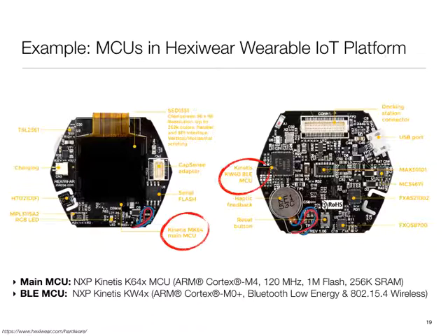It took the motion sensor data and continuously computed what you were doing, like how many steps, are you sitting, walking, stuff like that. But it was nothing other than a Cortex-M processor running specialized software. It was not visible to you as a programmer, but it still existed. So modern systems have a lot of these hidden processors, and then these application processors. That's the architecture out here.